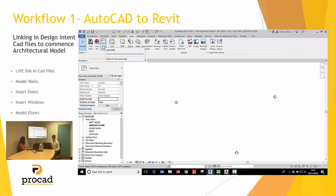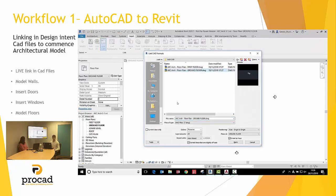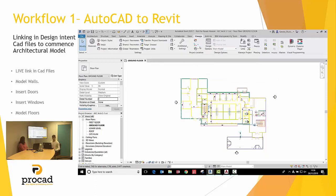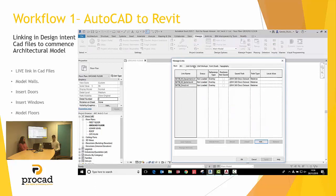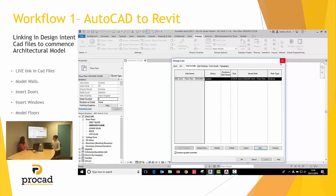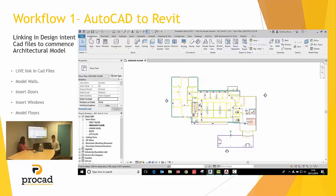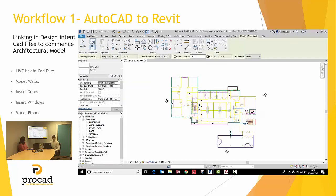From here, the very first thing I'm going to do is link CAD. Link CAD creates a live link between AutoCAD and Revit. So if any changes are created inside AutoCAD, it'll directly load into Revit through the Manage Links option. Inside here you can see Manage Links, and you can see through CAD formats that the AutoCAD ground floor plan is now linked in. The very first thing I'm going to do is create walls.